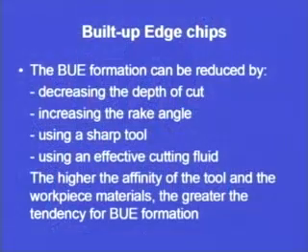Then using an effective cutting fluid. If we are using a cutting fluid, there are every chances that the built up edge may not form. Moreover, it can be reduced. The chances of formation of built up edge can be reduced by using an effective cutting fluid.